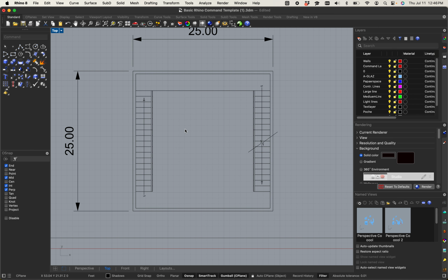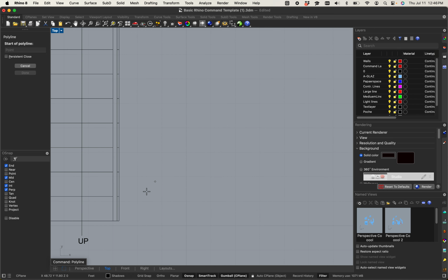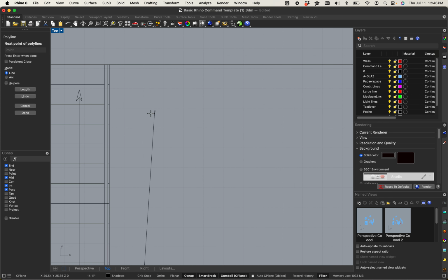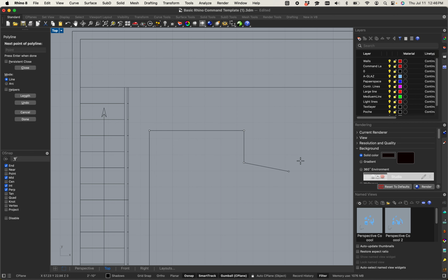Again, this is kind of a fictitious situation, but let's go ahead and make a polyline. I don't know, maybe I have this cool interior wall that's 12 inches, so I'm gonna type in 12. I'm gonna hold shift. I'm gonna get fancy with the spaces because mine is kind of a fictitious project, so why not? 24 inches out. Maybe the wall comes out over here. We'll go with 48 inches, enter. Yeah, that's a pretty interesting wall.